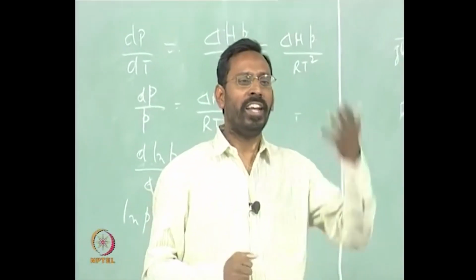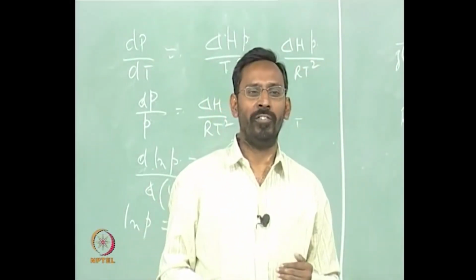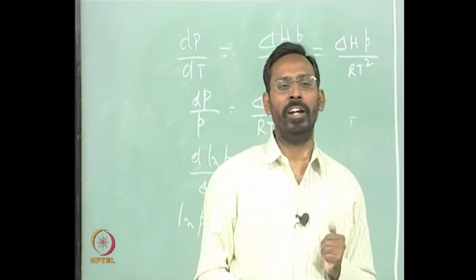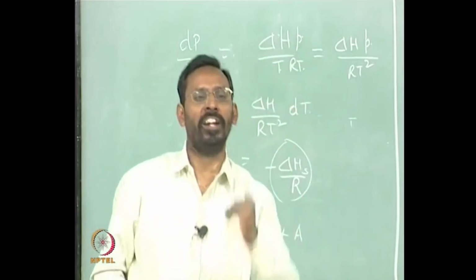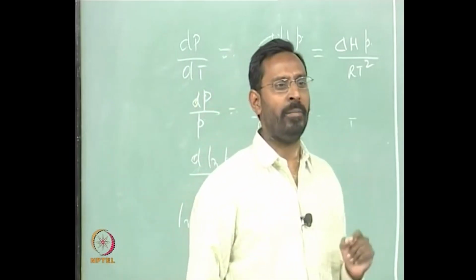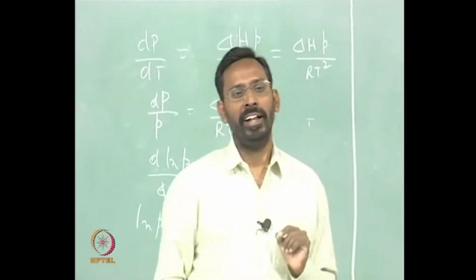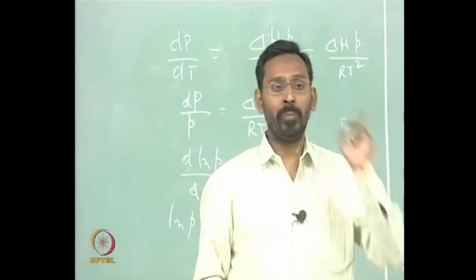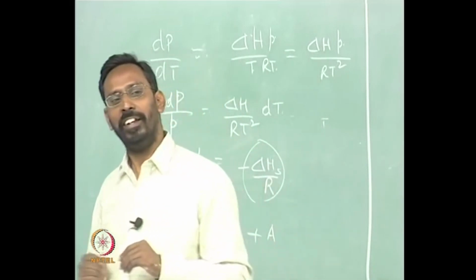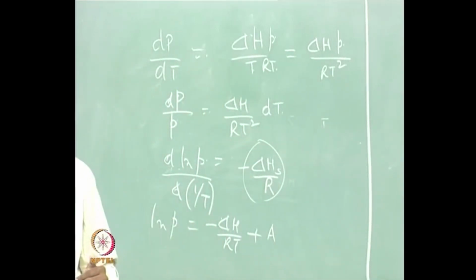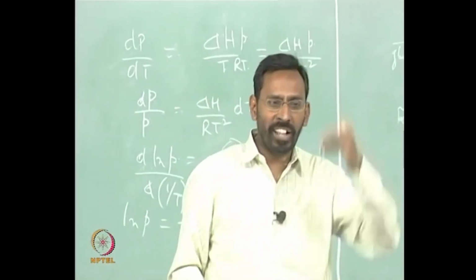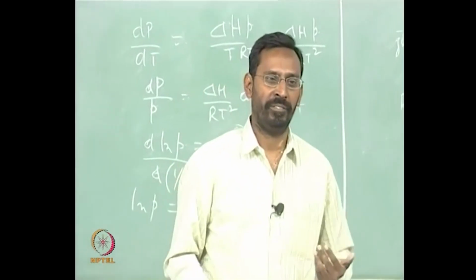This is similar to taking a liquid and cooling it very fast. It does not start solidifying at the normal equilibrium transformation temperature. Instead it undercools to a lower temperature and the transformation starts at a lower temperature. Exactly similarly, whenever I am heating the solid, in principle the melting point also shifts. The only difference is the shift in the melting point with the heating rate is not as much as the shift in the freezing point with a cooling rate.